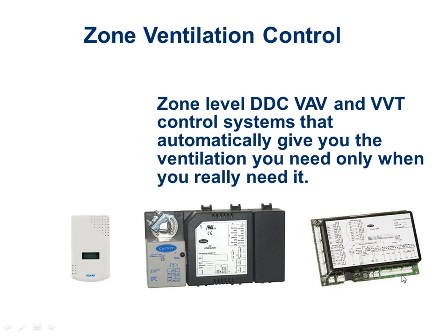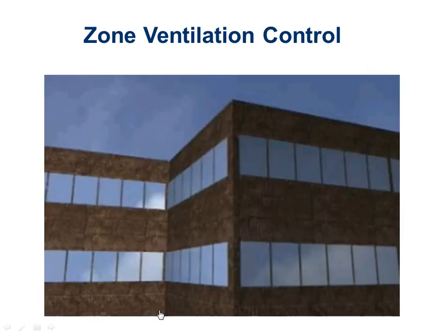So not only modulate its outside air damper based on CO2 levels, but in our case with a zoning system, go back and look at all of the zones combined to see which one of them is worst off and make sure that he's getting satisfied.